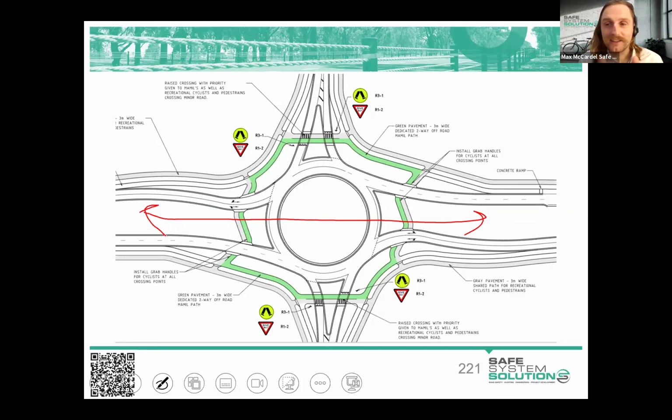So that's the east-west leg. If I look north-south, so look at this leg that's going on at the top of the screen, I wouldn't say that this has the same movement function. It's single lane, undivided carriageway. And we're kind of tying this into the movement and place that we were talking about before. And the reason I'm mentioning this is because the movement classification and also the place classification can then influence the way that you actually treat or recommend solutions.